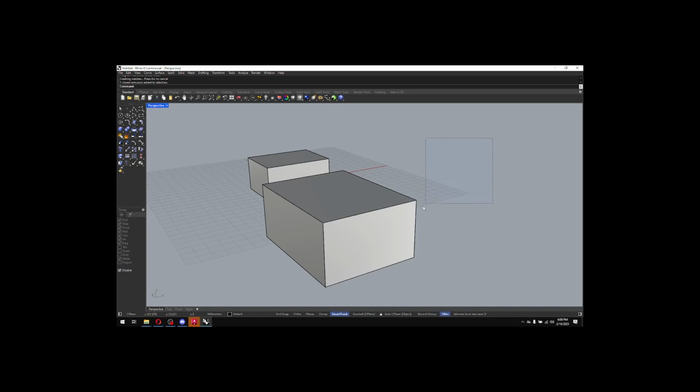If you go to the left, anything I barely touch gets selected. So you'll probably get into a habit of always going to the left. That's what I do. You just build in that muscle memory. But that's the left mouse click and hold. If you just click it, it doesn't do anything. Actually, left click, if you just click it and let go, acts like enter or spacebar. So I actually use that to start and end commands, things like that.